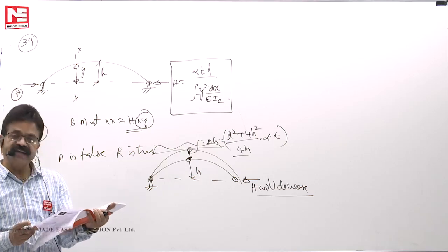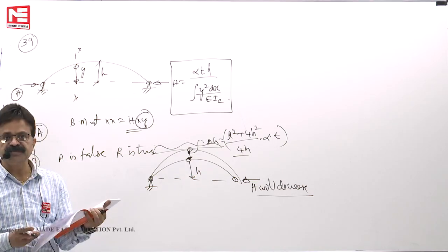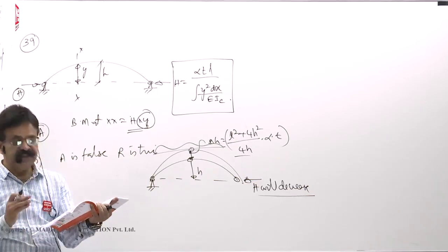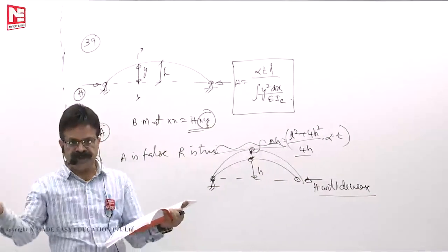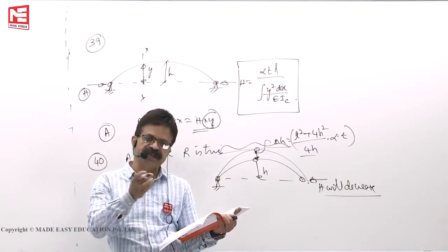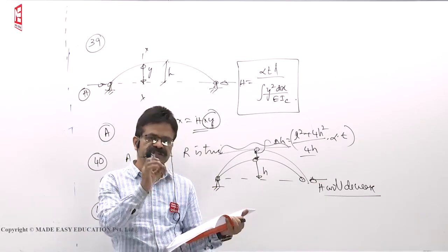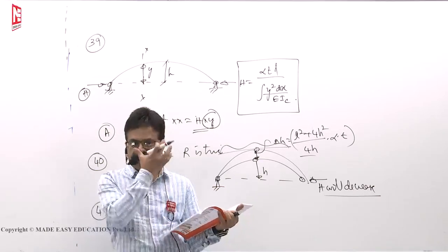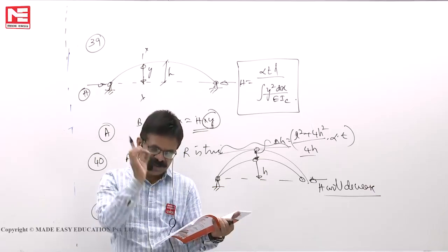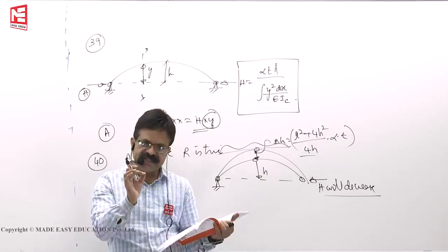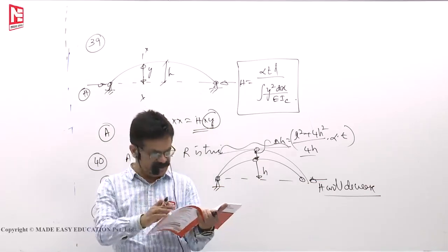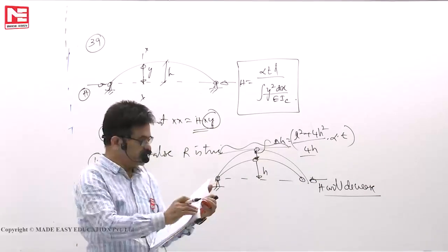Both statements are correct, and the explanation is also correct. In a parabolic arch, the bending moment at any section means the funicular polygon. That means if you build any arch which follows the shape of BMD, then it is called a linear arch, and the cross section is subjected to only normal thrust. In such cases, if you draw ILD, you will get positive area and negative area balanced. Okay, 41. 42.